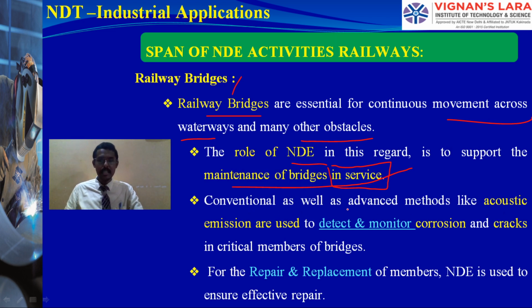Conventional as well as advanced methods like acoustic emission are used to detect and monitor corrosion and cracks in the critical members of the bridges. Bridges are over waterways, therefore there is a lot of chance of corrosion. Therefore, they should be subjected to continuous inspections. For repair and replacement of the members, NDT is used to ensure effective repairing. So that is one of the important cases.